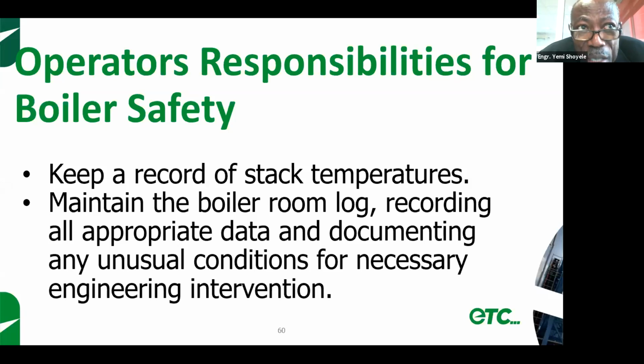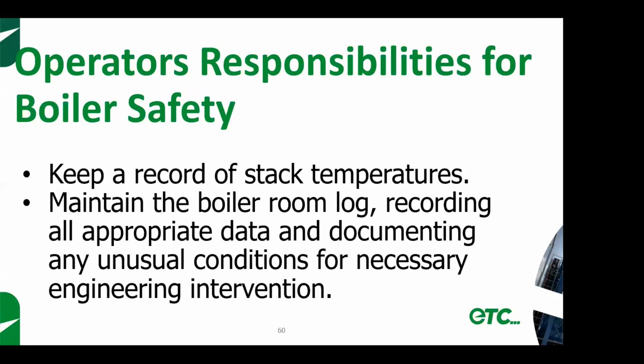If you don't have a degasser, you just need a degasser. Because that's a simple truth. You need something to agitate the condensate or whatever. You need some physical agitation, either by gas or whatever. You just need it. If you don't, then you'll be having too much high oxygen, and then of course your pipes will be corroding very, very quickly, on the water side of the boiler as well. Okay. You just need it. You just have to have a degasser.